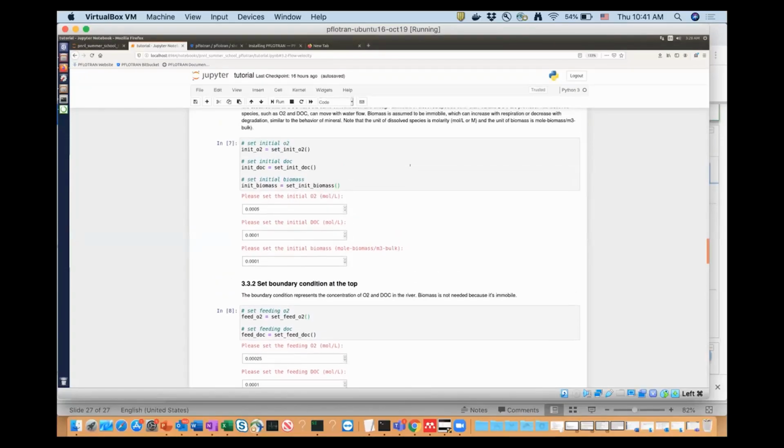But if the model domain is pretty big, for example, as shown in the presentation, we probably need to increase the grid dimension. It depends on your computational capability. If you have more computational resources, you can choose a smaller grid dimension, and then you have more information for the species, flow, or heat transport at specific locations in your domain. If you don't have that many computational resources, you can increase the grid dimension to reduce the simulation time. It depends on the model size and your computational resources.